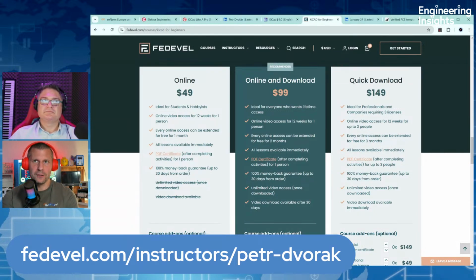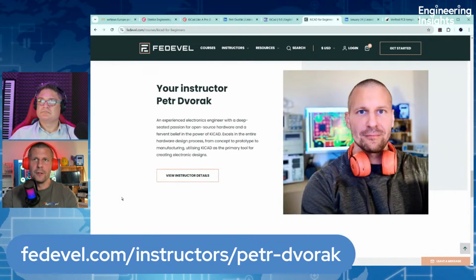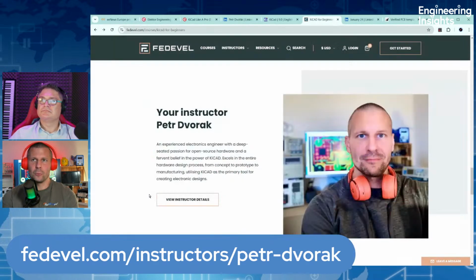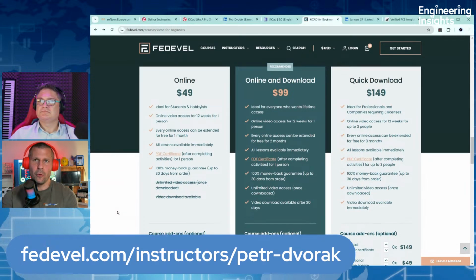I compressed everything into a 2.5 hour format. You will see how to create symbols, how to create footprints, how to create and manage symbol and footprint libraries, how to capture a schematic, how to lay out components on the board, how to route tracks, how to export manufacturing data, and how to export the bill of materials. And even in the 7th stage of the course, you will see that the board you just designed is working, because there is footage of me testing the board.